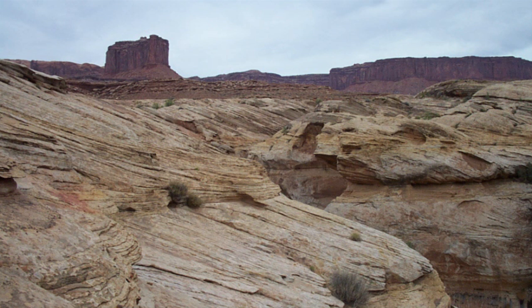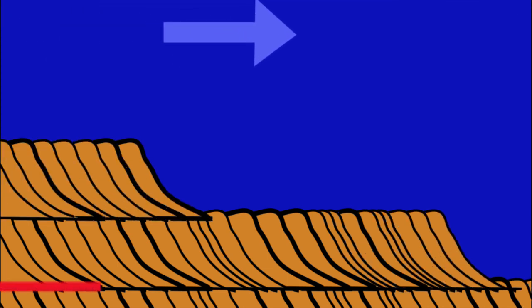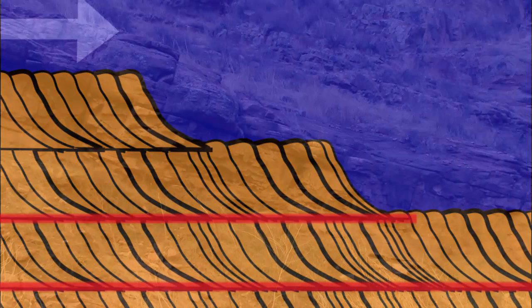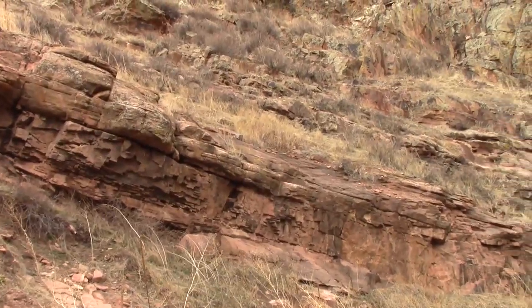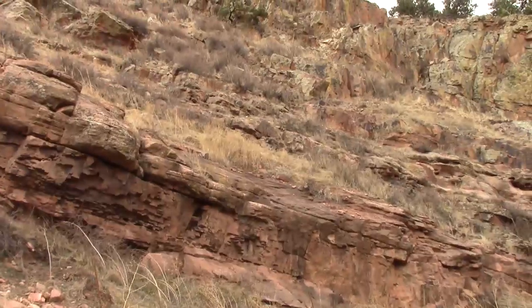But even if a sedimentary rock has crossbeds, we can almost always find an actual bedding surface. Recall that crossbeds curve so that they meet the upper bed with sharp angles closer to 90 degrees and blend in at a lower angle at their base. By recognizing these bounding surfaces, you are seeing the actual bedding plane of that layer of sediment. If such a bedding surface is exposed well enough, you can take a measurement.